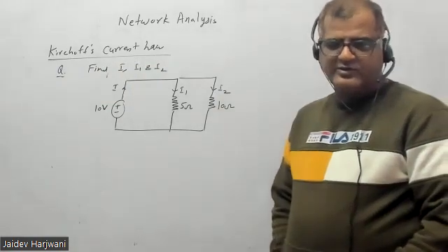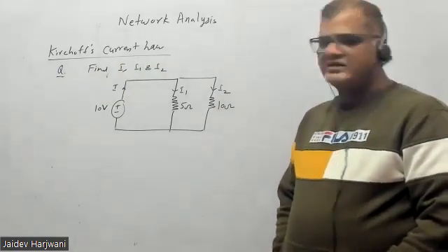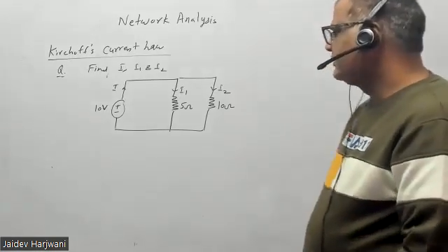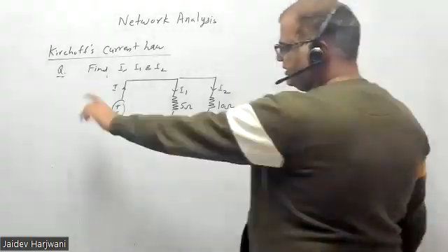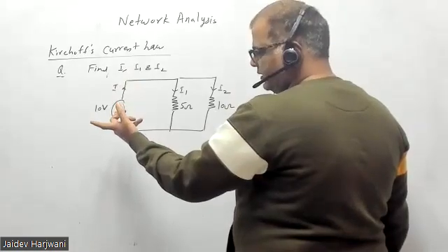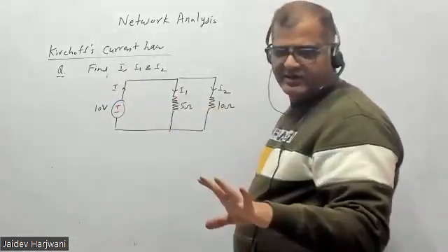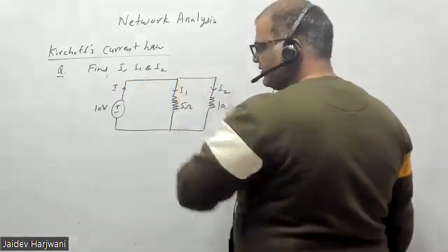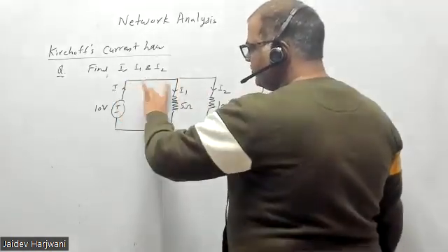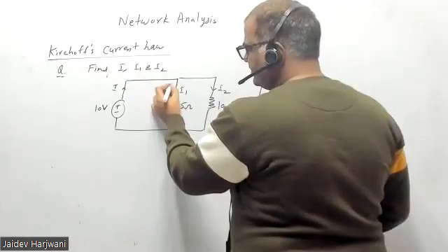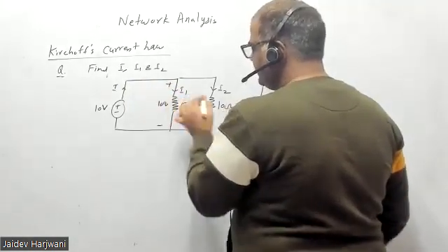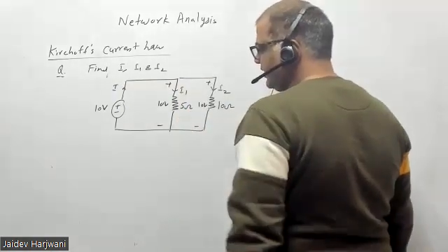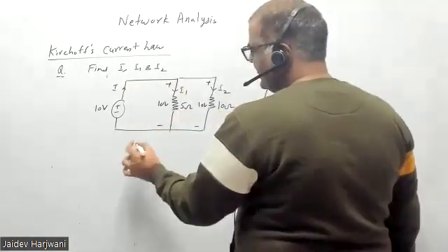Directly just look at the circuit. 2, sir. 2. Very good. You know Ohm's law, so I will use only those things which you have learned. These resistors are parallel, so if this is 10 volt, obviously here is also 10 volt, because they are all parallel.